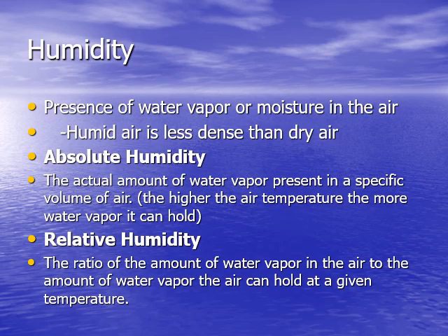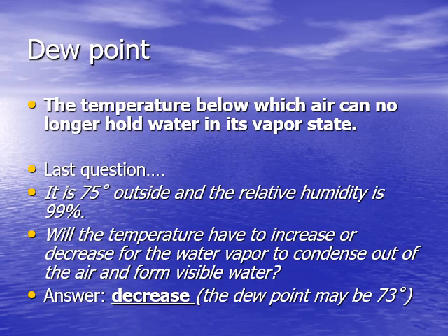Humidity is the amount of water vapor in the air. Since water vapor is lighter than air, increased humidity reduces air density, which can adversely affect aircraft performance. Dew point is the temperature at which air becomes saturated and water vapor condenses. If the temperature drops below this point, visible moisture forms. This has implications for carburetor icing, fuel system ventilation, and structural icing.